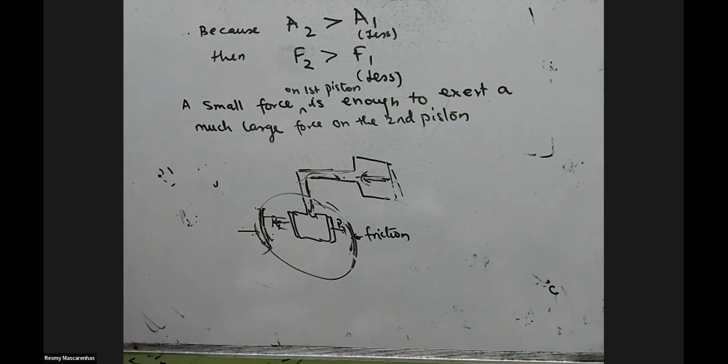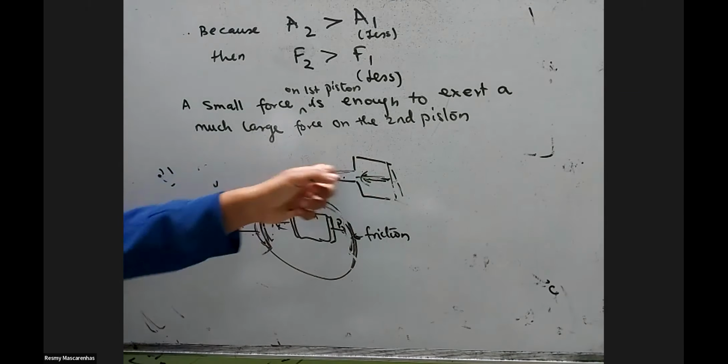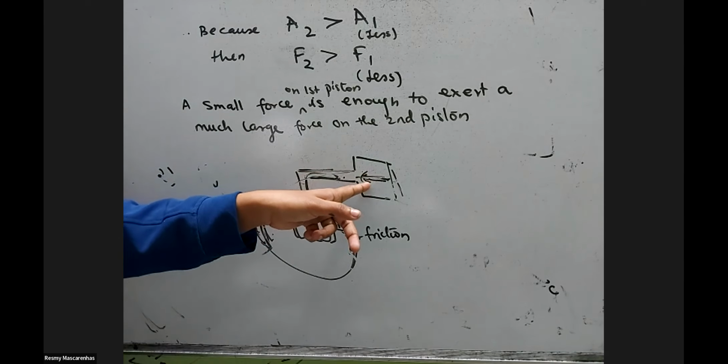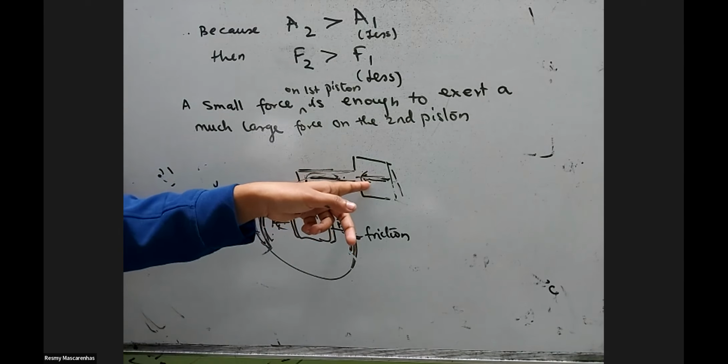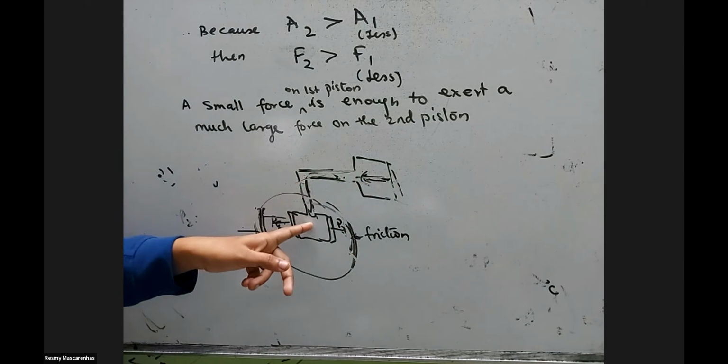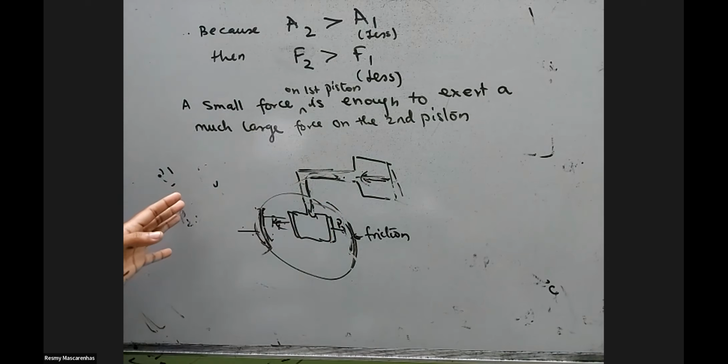Then the two advantages are given of hydraulic brakes. Hydraulic means whenever you are using this particular system, putting this fluid inside, an equal pressure is created on both the wheels. So you can always avoid skidding of the vehicle.